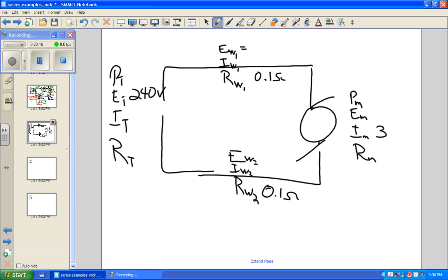It's drawing 30 amps. And the thing that affects voltage drop most is the cross-sectional area of the wire and the current. So the current is what we're looking at here. Now, in a series circuit, the current is always the same, right? So we're going to plug in 30 amps, right?